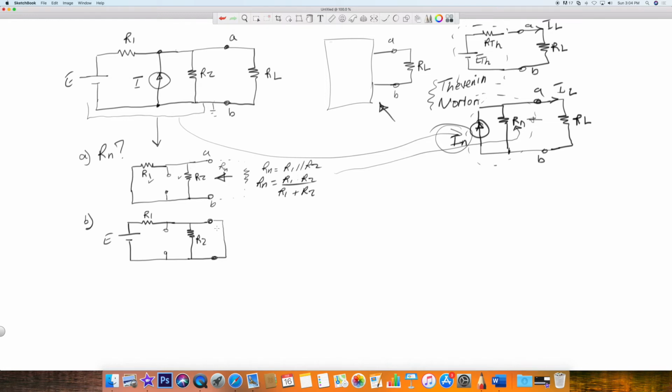Okay, so if we have a short, that means the only current going through the circuit is obviously going to bypass R2, so all of your current is going to go through the short. So R2 is not going to get any current. That same current obviously is coming from somewhere, so it's going to traverse R1. Aha. So let's call this one I Norton 1 right here. And this will be the same here, I Norton 1, generated by this power supply.